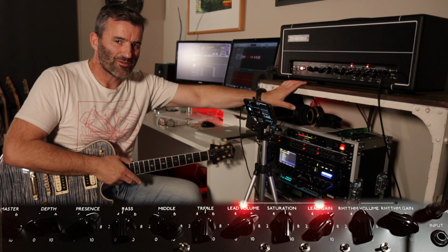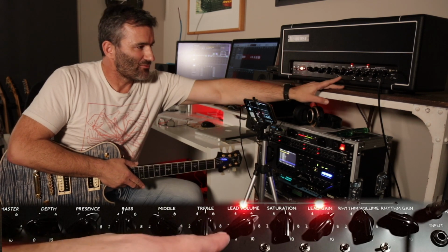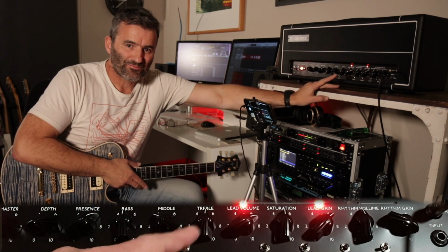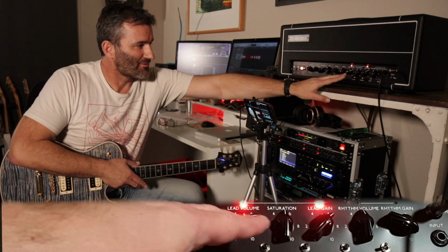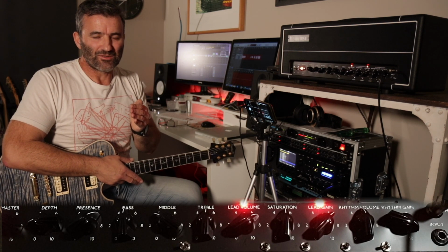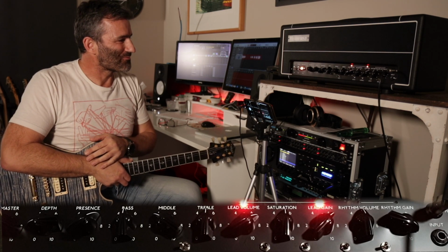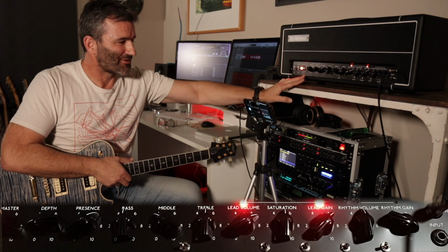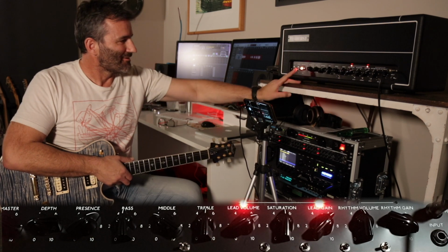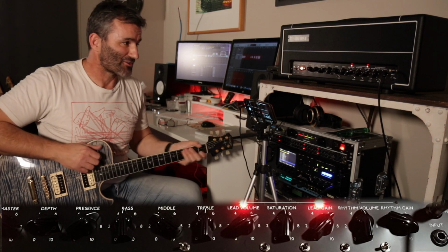It's always worth noting that in these Wizard style amps, similar to the Marshall Jubilee, these channel volumes aren't at the end of the preamp. There's another gain stage that follows these volumes. So if you run these channel volumes very low, you're not going to be driving that last gain stage, and you're kind of missing out, I guess, on that extra bit of push. So I find the Global Master's a really good addition to these, because you can crank these channel volumes as if you had the amp really cooking, and still end up with something that's from a volume perspective at least you can control.